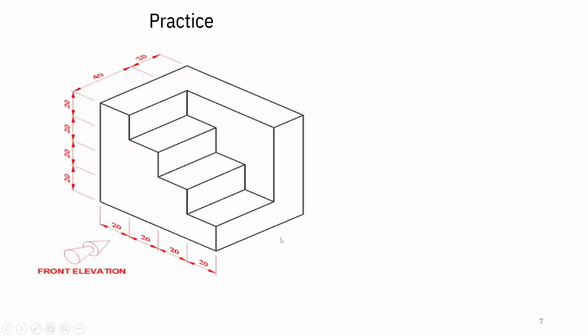In this case, for the given object, we see that the front view or elevation is shown by an arrowhead, this arrow. And this is the direction in which we can obtain the right hand side view, and while the observer is standing here and looking from the top, the observer will be able to draw the top view.